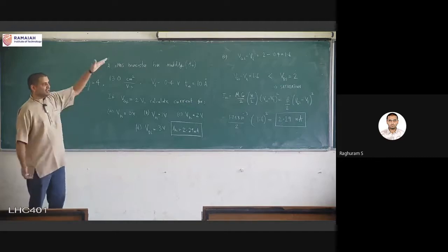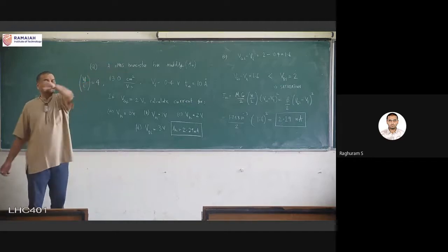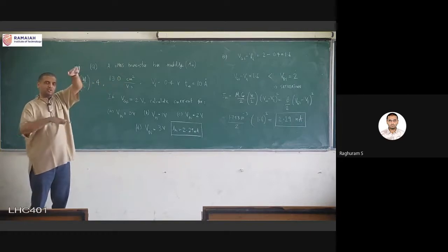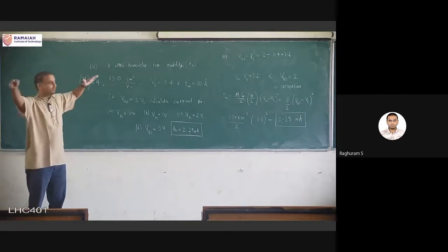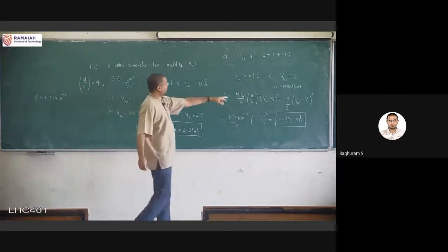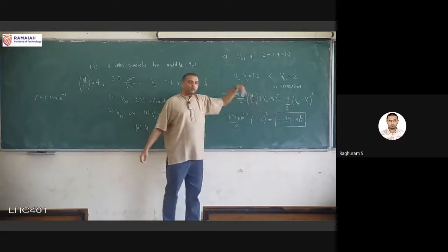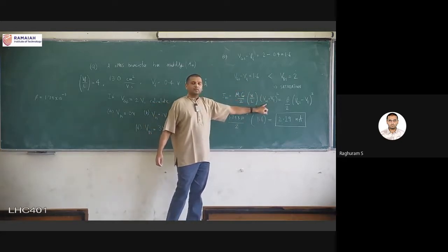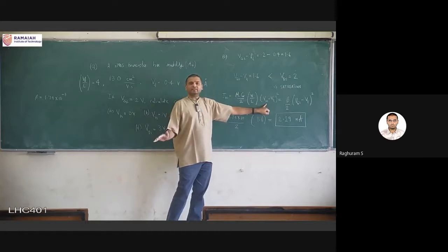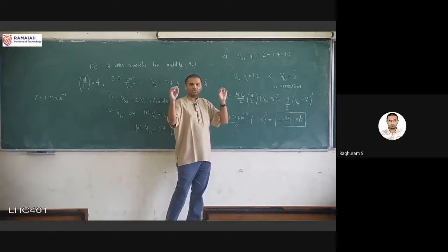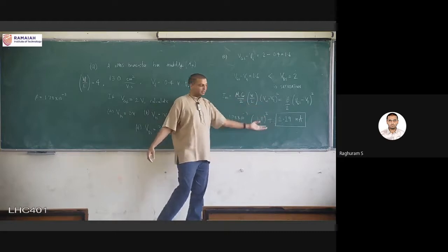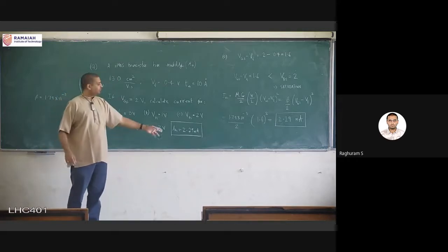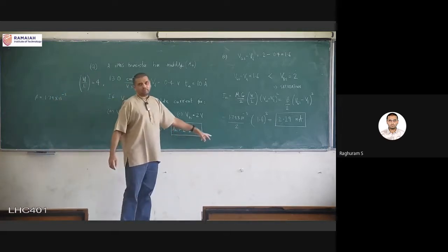In the saturation region, if you remember, the current is a flat value. VDS is the x-axis. VDS keeps changing, but the current stays at the same value. Because in this equation, which is the equation for all of the saturation region, the current equation does not have VDS, which means that it is going to stay at a constant value. What is that value? We have just calculated. So for different values of VDS, if given, you can very quickly write it off. The same value will continue.